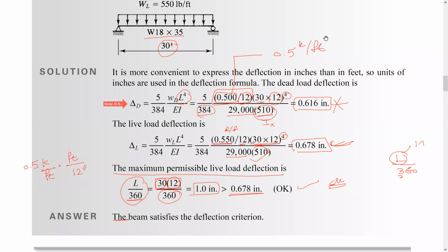Okay, so you should be able to check the deflection for any type of beams using table 3-23 in the steel manual, the one I just showed you, or for any type of loading. So let's move right now to the design of the flexure elements. Let's move down.